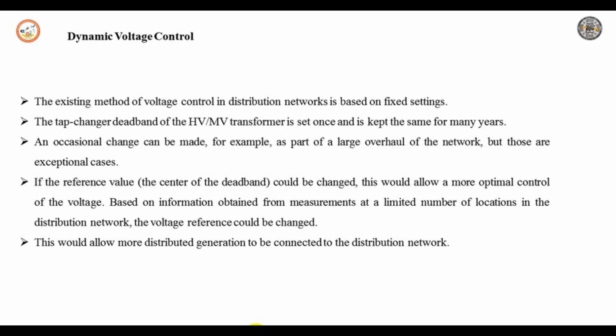Here, field experience of an 11 kV network in the United Kingdom is described, where the voltage and power of 5 feeders with 2.5 megawatt wind parks are used as an additional input to the controller. Both the overvoltage and undervoltage margins are calculated, assuming that the limits are 94% and 106%.